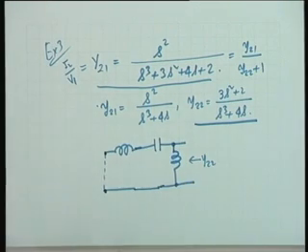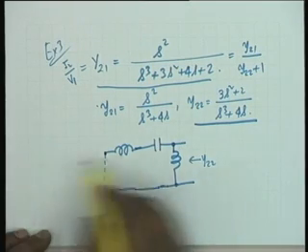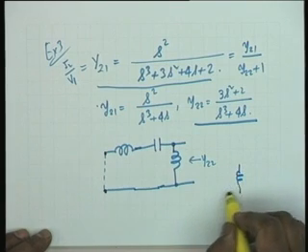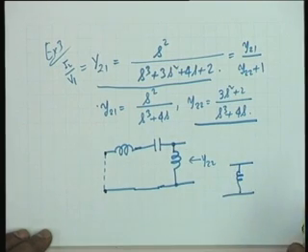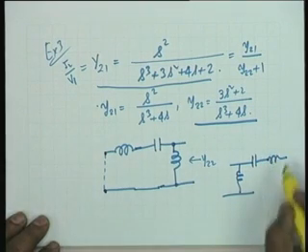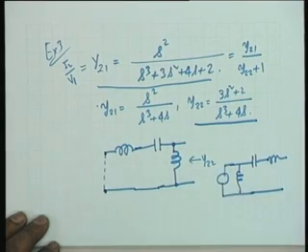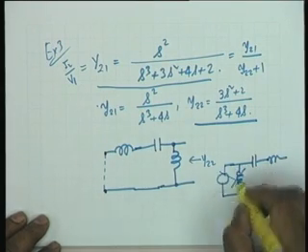Excuse me, what will happen if we have the parallel inductor first, then a capacitor in series, then an inductor in series? Say it again. A parallel inductor first. Parallel inductor, what does that mean? So looking from this side. Yes, so if we have first an inductance in parallel, in shunt, right? Then a capacitor in series. Then an inductor in series. Well, this will not do the job because there is a voltage generator here. This inductor will therefore be ineffective.